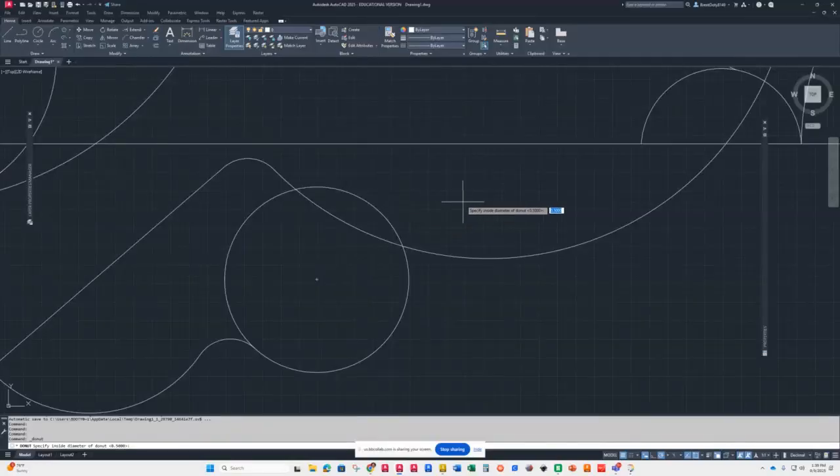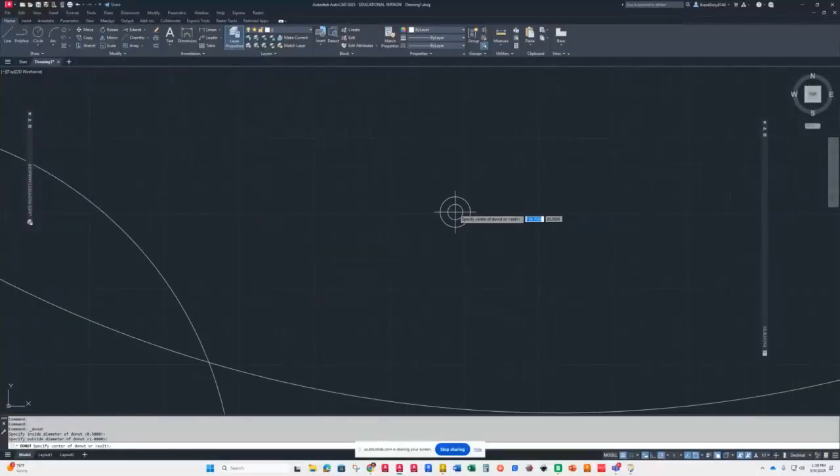So if you have a donut, you can make a car. What's the first thing I drew whenever I was learning how to use AutoCAD? I drew a goofy Beetle. Volkswagen Beetle, because it was real easy. It's arcs, you know, and a couple of donuts. I got wheels. So usually what I do is I show people, I say, oh, well, you can draw donuts. So you can do, let's say the inside's 0.5, the outside's 1. And so there are my two wheels, right?